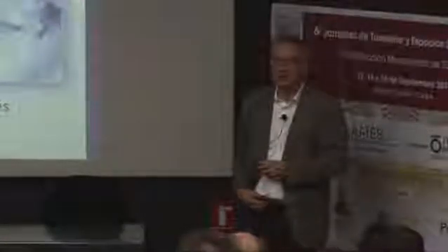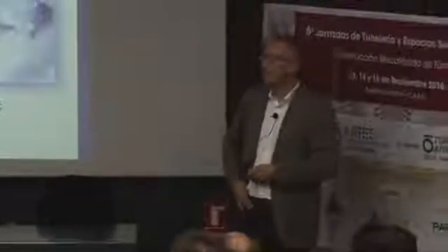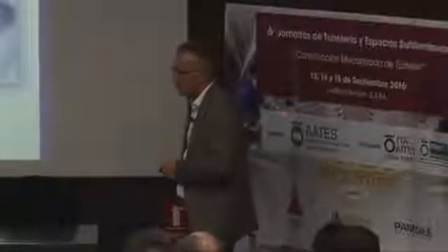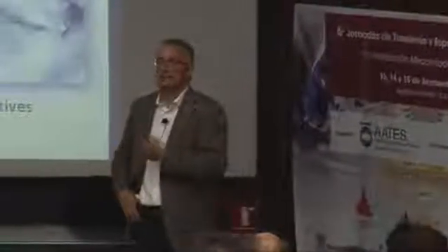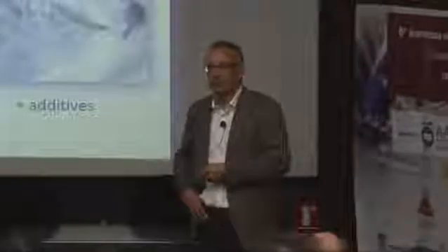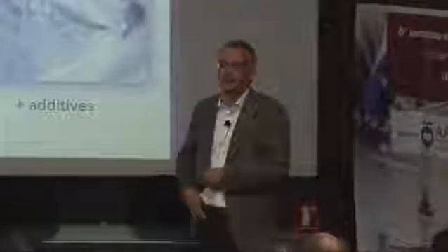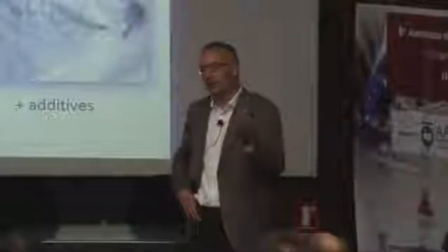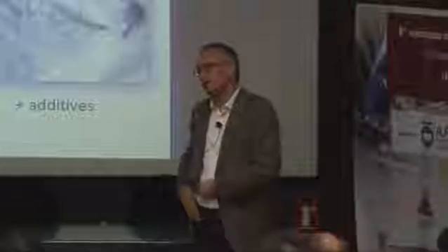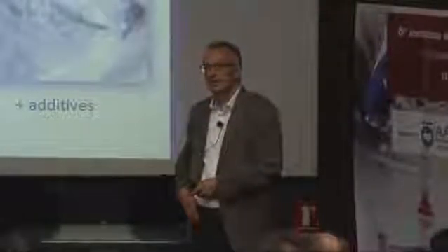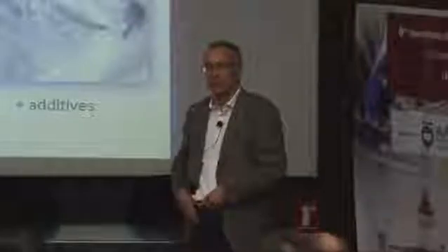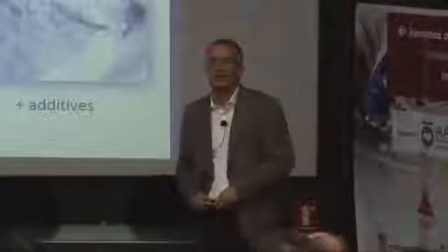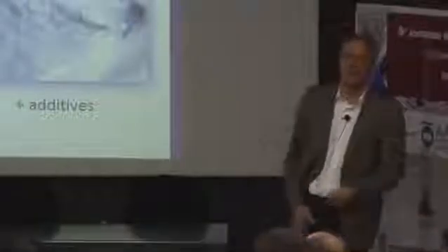You make those tests, as already mentioned, in a laboratory, where you use different parameters and make a study with different amounts of water, different additives, and different volumes of air to find the best mixture for your EPB TBM operation. Later during operation, you have to control what the outcome is out of the screw. You see on some TBM parameters, you can get quite a good idea how the material behaves and if anything is changing.